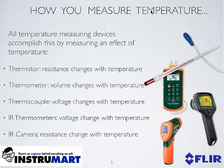Thermocouple device, a thermometer, thermistor, an infrared camera, and a spot radiometer or IR thermometer gun. These measurement technologies and what they truly measure, for example, a thermistor measures changes in resistance associated with changes in temperature. A thermometer measures changes in volume associated with changes in temperature. A thermocouple measures changes in voltage associated with changes in temperature. IR thermometers also measure changes in voltage associated with changes in temperature.